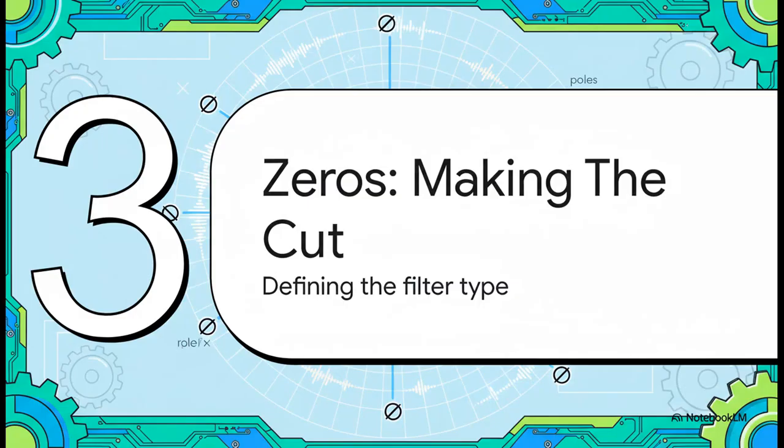Okay, that's pretty cool. So poles make peaks. We got that. But what if we want to do the opposite? What if we need to cut a frequency? Well, for that, we need our second tool, zeros. And zeros, this is where we really define the basic type of filter we're building.